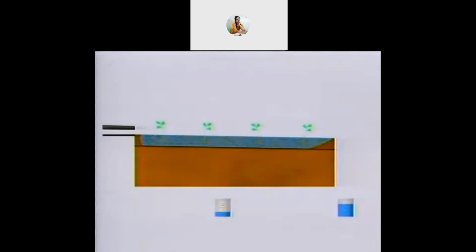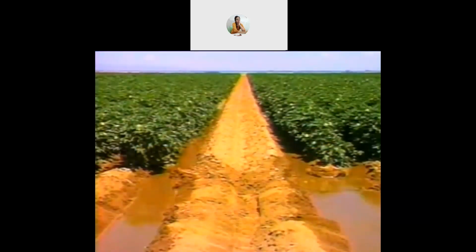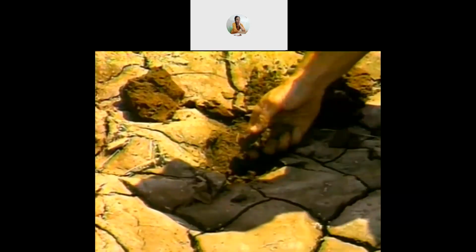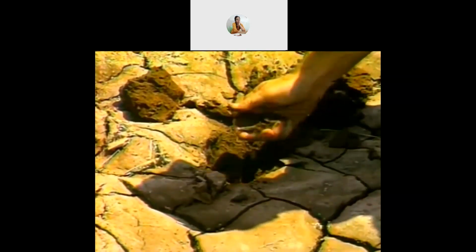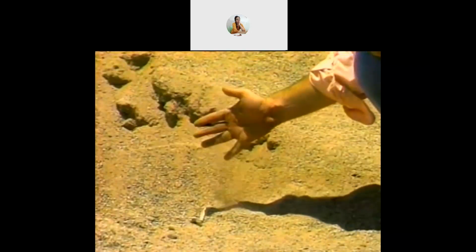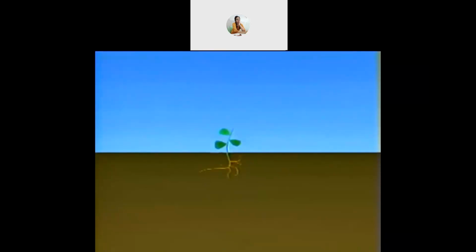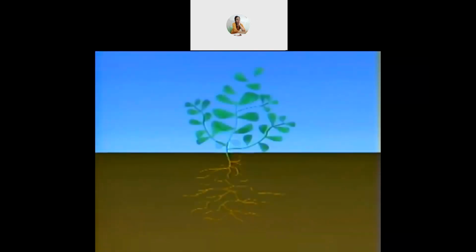The best flow rate depends on the slope and length of the field, the type of soil, a heavy or clayey soil, or a light or sandy soil, the condition of the furrows. Dirt clods and plants will slow the water down, and the depth of the root zone. Early in the growing season, the root zone is very shallow and not as much water is required.